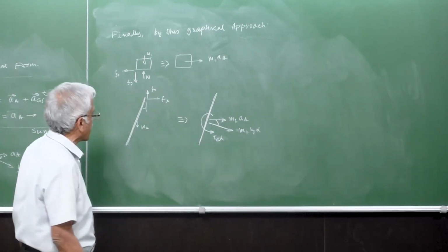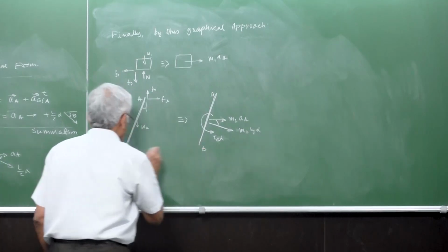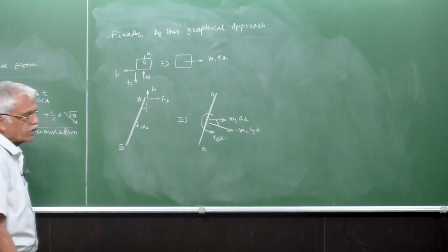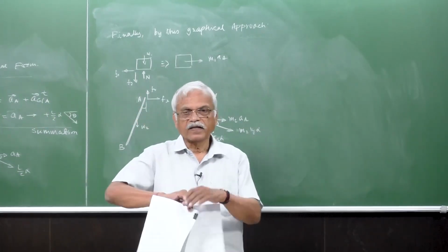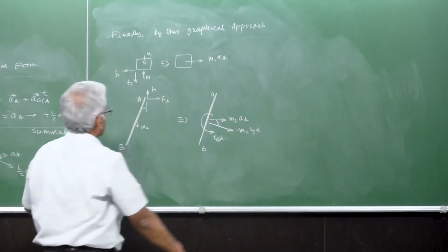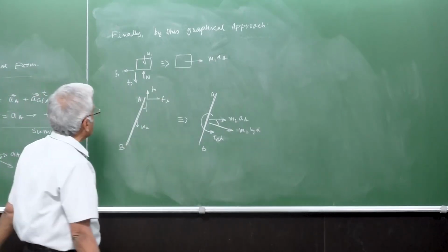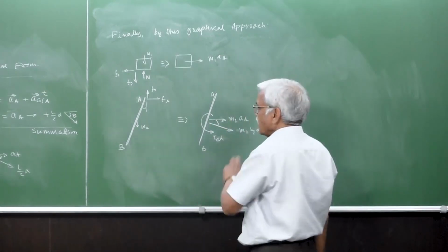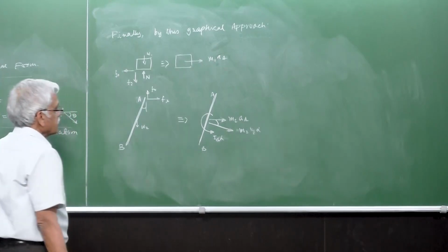This is how we write it again in a graphical manner, by simplifying the depiction of the acceleration of G. Now you can see very nicely that this gives you two equations. There are only 5 unknowns: Fx, Fy, N, a, and alpha. That's all. So you can write down these equations.